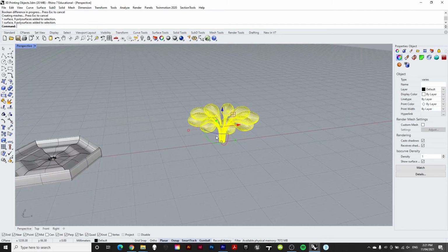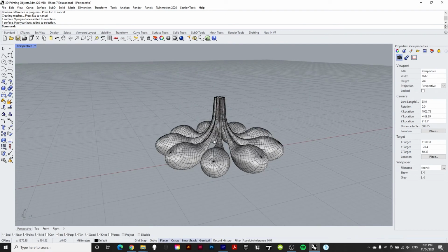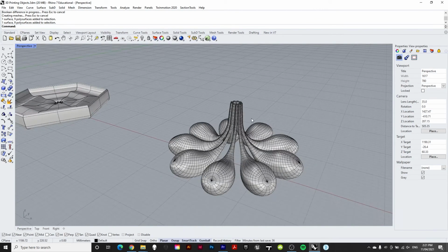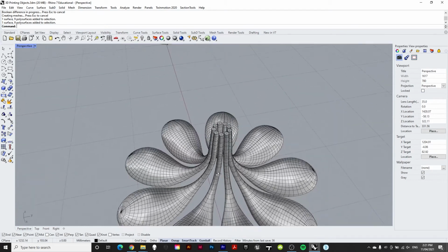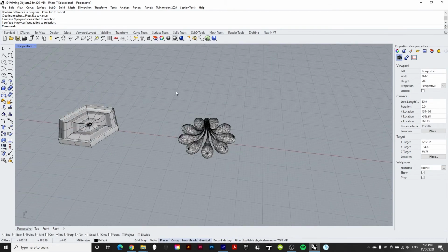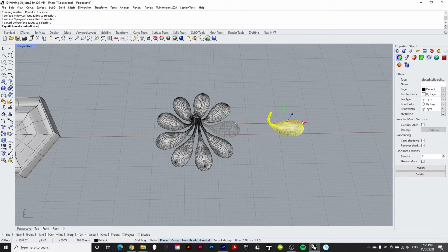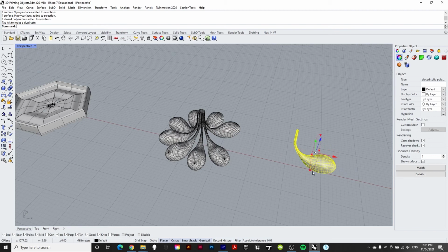We could turn it over by 180 degrees and have it made this way, but we'll still end up with a lot of struts inside there that we're going to need to clean out, and it's going to get pretty hard to do once we get into this tight geometry we have up the top there. So what I would actually recommend with an assembly unit like this is to get each part 3D printed individually, just like we have here.